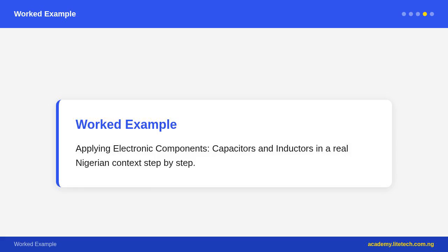Remember, capacitor equals electronic component that stores electric charge and electrical energy, plus releases when needed, consists of two conducting plates, electrodes, separated by insulating material called dielectric. Charge builds up on plates, electric field in dielectric. Capacitance equals measure of ability to store charge, symbol equals C, SI unit equals farad, F. In practice equals microfarads, μF equals 10^-6 F, plus picofarads, pF equals 10^-12 F. Formula, C equals Q/V, capacitance equals charge/voltage.